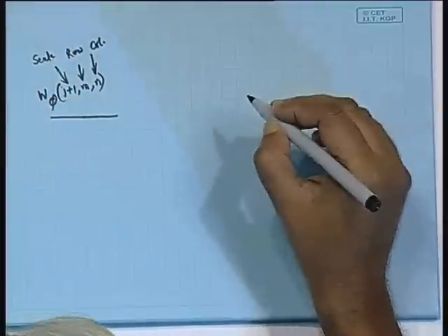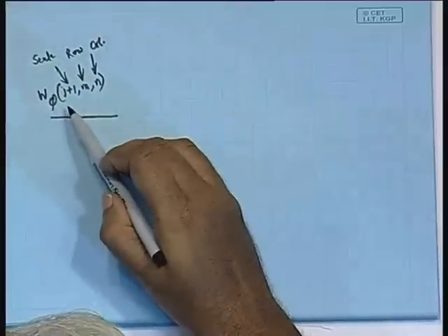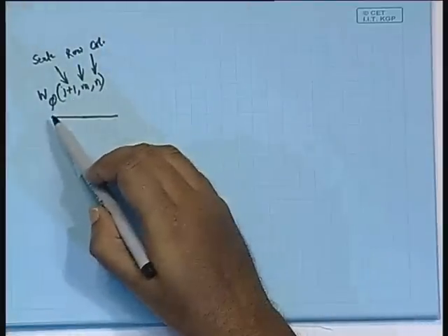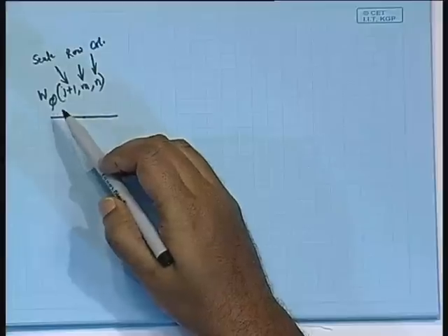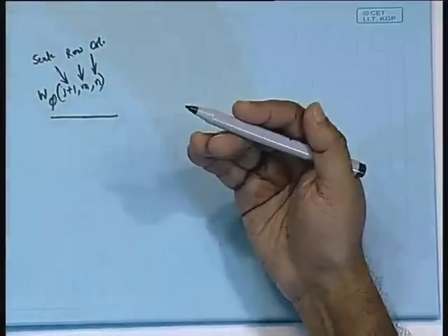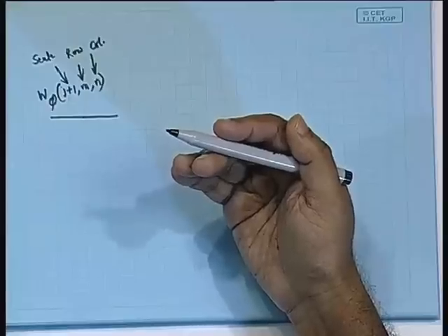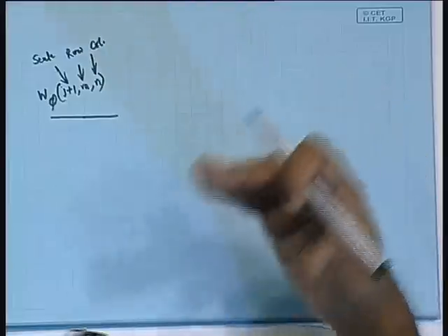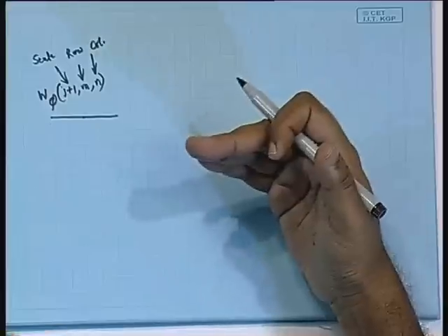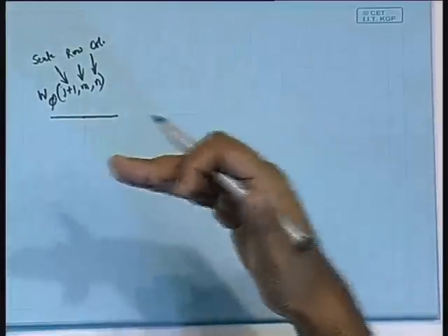And from W phi j plus 1 m n, the suffix phi indicates that it is the scaling function. That is, it is after application of the scaling function, which means it is the low pass filtered version of the signal. When applied on two dimensions, the subband we get by filtering the image as low pass along the rows and low pass along the columns is the LL subband, the picture which we had shown in the last class.